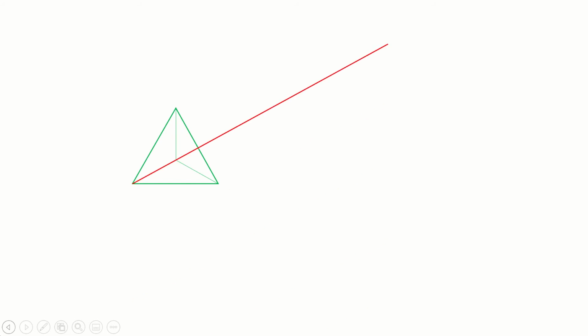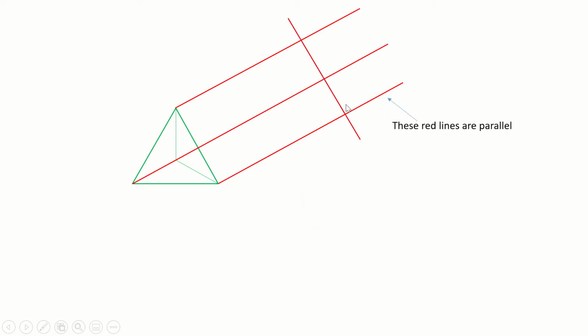So our first step is going to be projecting the lines into elevation. Again, as I mentioned earlier, these lines must be kept perpendicular to this side of the crow's foot. We will then draw a line perpendicular to these red lines, and the distance away will be h. On an A3 sheet, this distance from here to here is usually between 50 and 100 millimeters, but this is at the student's discretion.